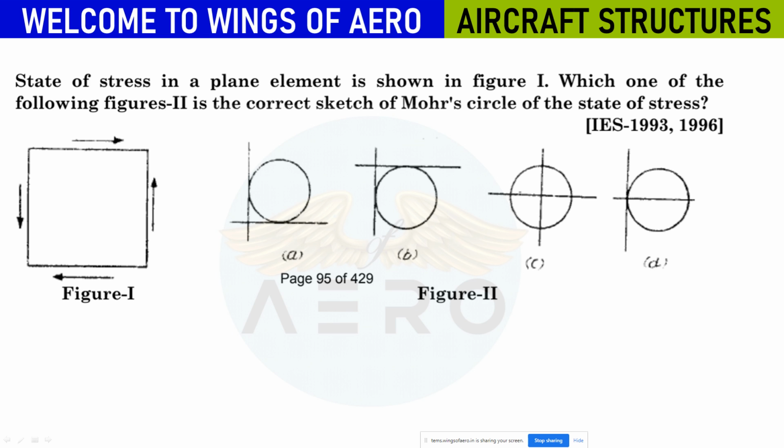So understand the importance of the diagram. If they are adding some kind of direct stresses, that means it will become bidirectional with shear stress, and then the figure will be different. This represents only the pure shear. So pure shear means option C. I think that's all the questions.